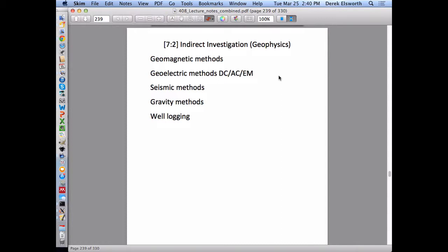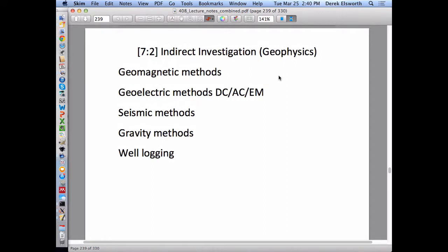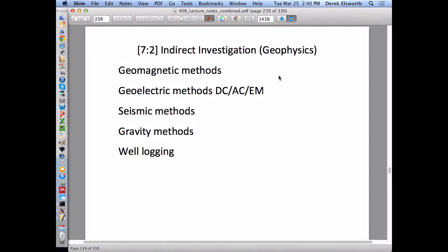And so the other way to fill in between things is by using geophysics. And geophysics is best used where you have an initial borehole as confirmation or some kind of profile of confirmation. You run the geophysics, it looks at some particular proxy, and then you benchmark it against that hole and you extend it to the other locations to be able to infer what's there. We talked about a few of them. They all work by this idea that they look at a proxy.